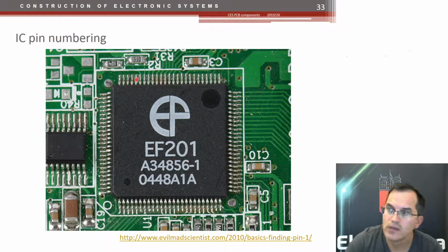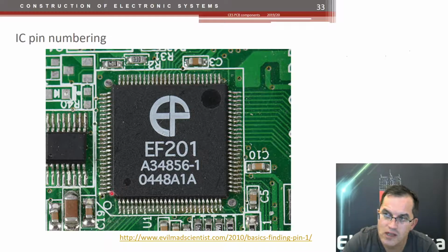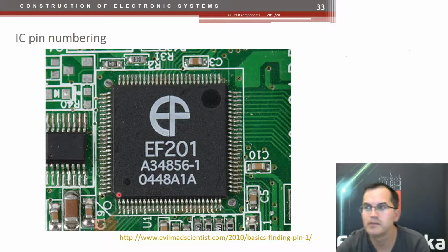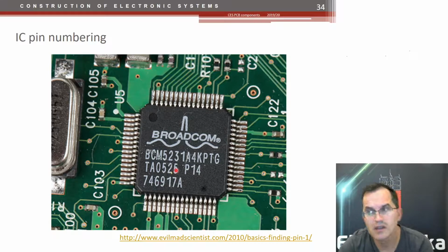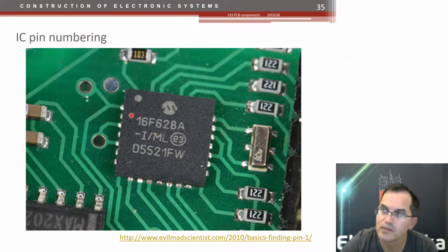Here is pin number 1. You see two markings, so we have to rely on the corner, which is chipped off here a little bit. See, sharp corners, and here we have a round corner. Pin number 1. Here, pin number 1 is here. So the letter or text orientation is not always the same. So here is pin number 1. And here, pin number 1 is here.